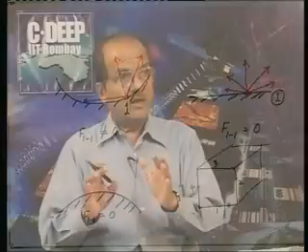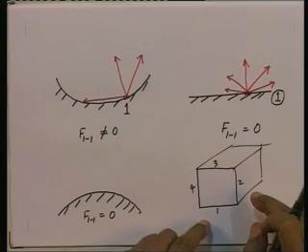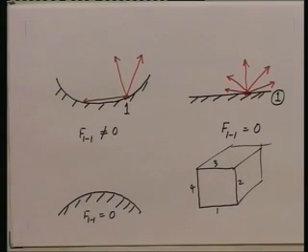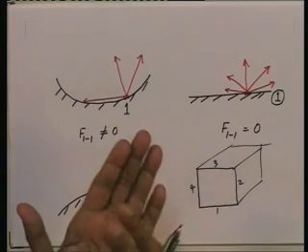Now, if I treat the 6 surfaces as surfaces independent of each other, F1 to 1, F2 to 2, F3 to 3, all for each of these surfaces will be 0. But let us say surface 1 and 2 are at the same temperature. So, for purposes of calculation of radiant heat exchange, I can treat 1 and 2 as one surface, all right.